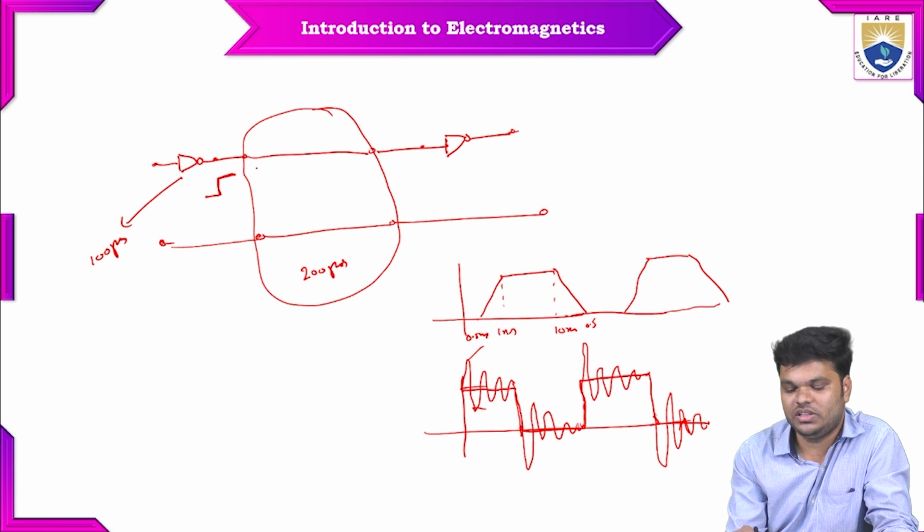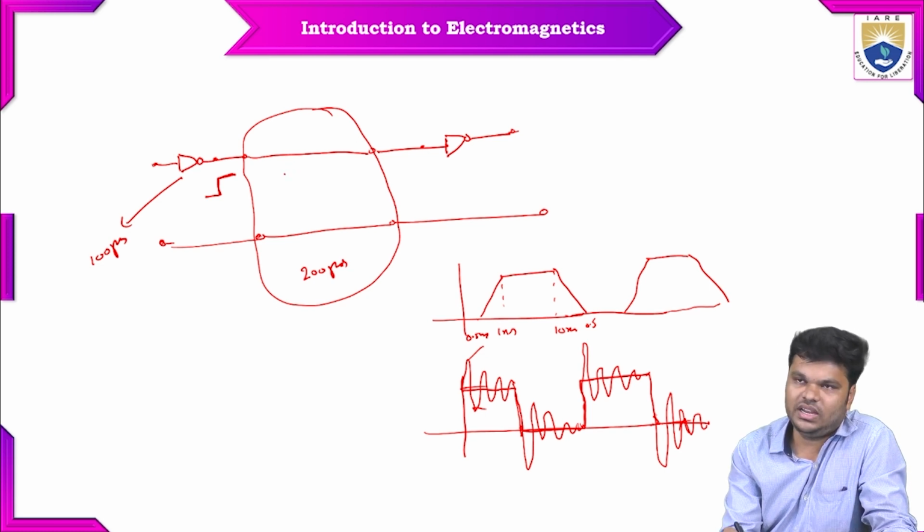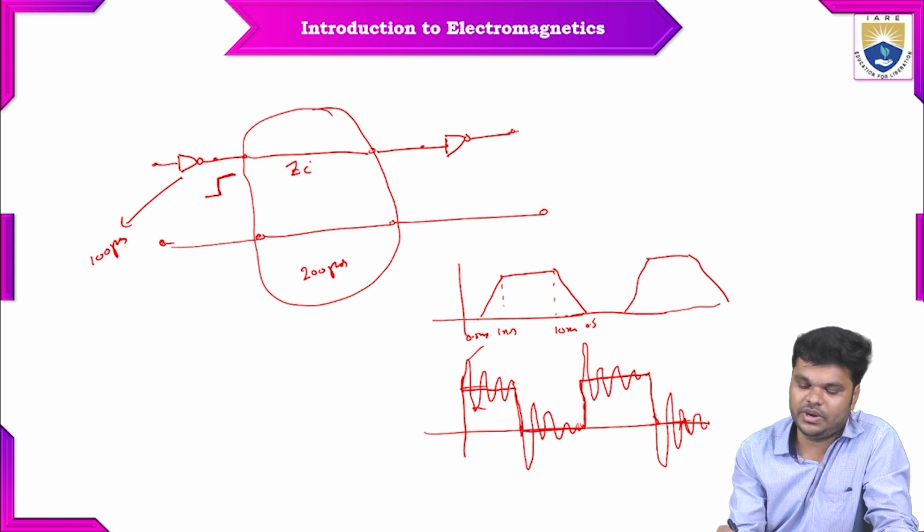As I have already told you, this is an interconnect and this is a transmission line as well. Every transmission line is characterized by some parameters like characteristic impedance and time delay. We know that this pair of wires causes some delay. So there will be some time delay when I connect these two logic gates with these two wires, right?